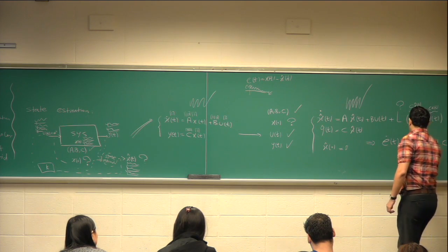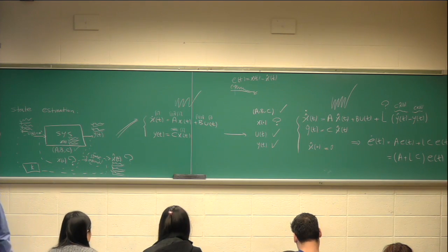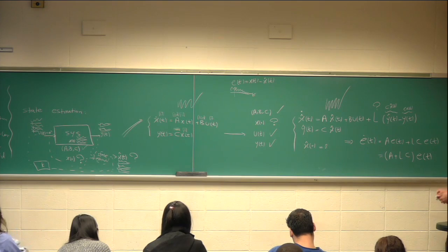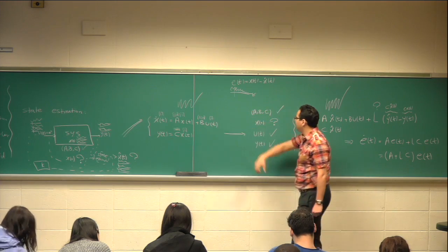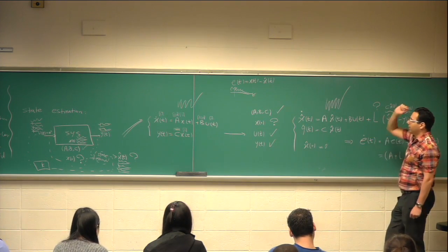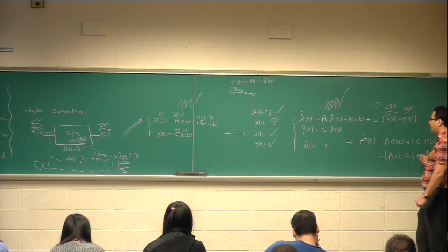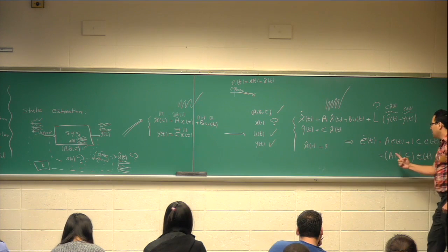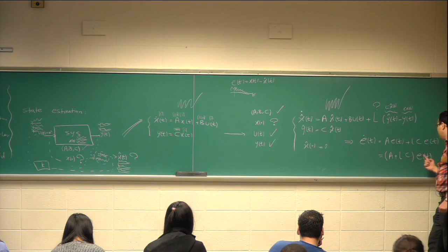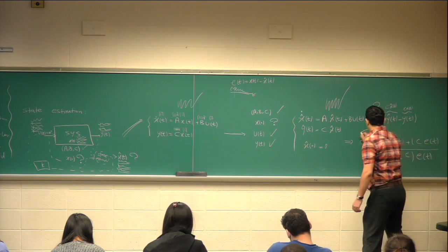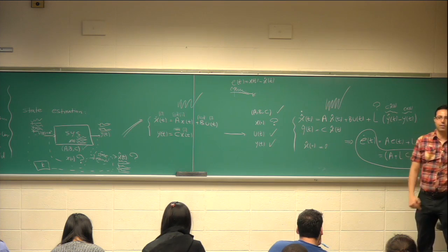If we do the simplification, the dynamic for error looks like this. So they really needed estimators for many reasons during the war. You have a system, which could be a gigantic system or a small system. You want to estimate the behavior. You try to simulate it by starting with 0. You have a correction feedback, and then you take the difference. What is the dynamic of the error? The derivative of error is A plus L, that you're going to design, multiplied by C, multiplied by E. How can I make sure that for a system with this dynamics, error goes to 0?